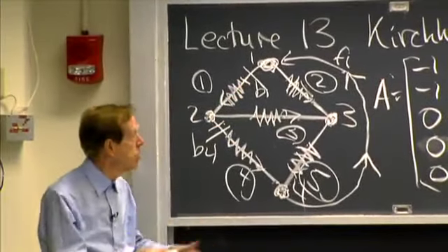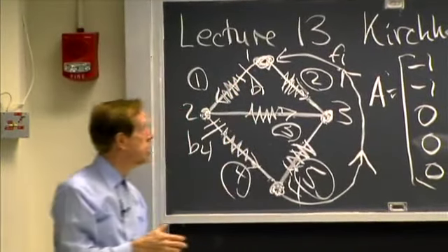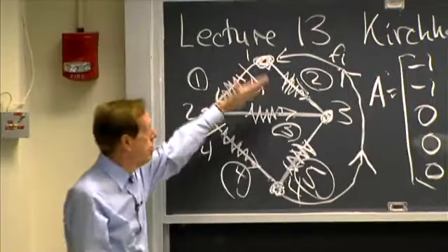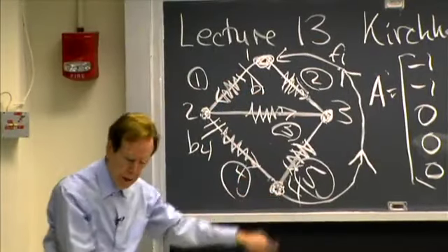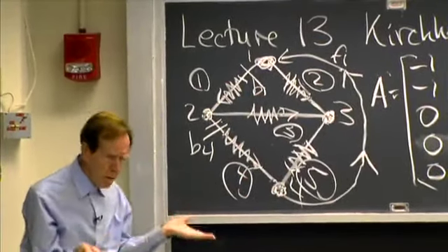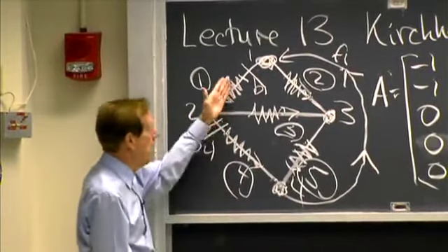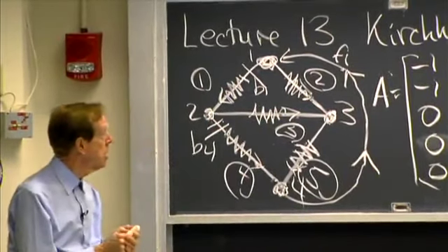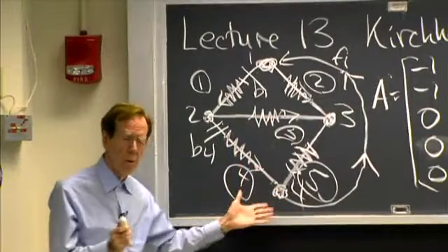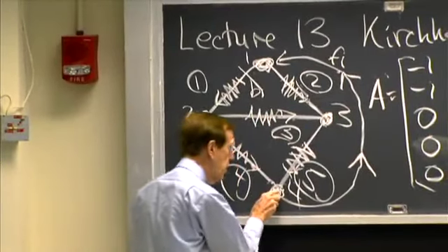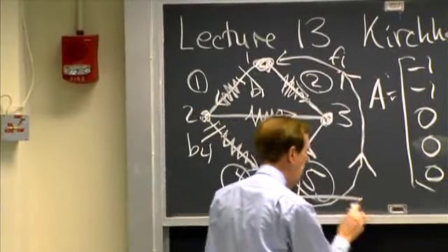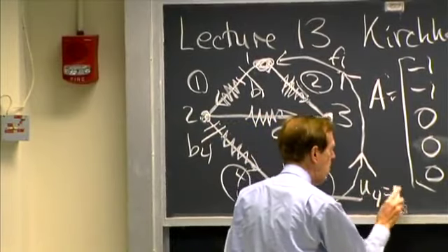If I imposed a current source, if I send a current source through there, it would go down and come out at ground. And our question is, what are the currents in the 5 edges? What are the potentials at the 4 nodes? Well, I'm making this one ground, so I'm grounding this one to be U4 equals 0.